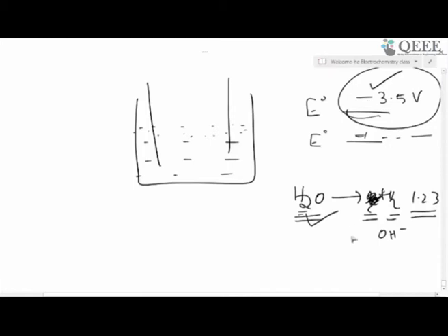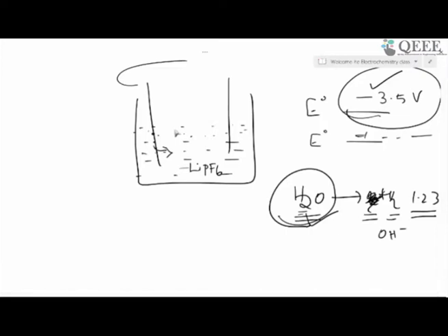To prevent this, we need to use an electrolyte such that this reduction does not happen. So that is why non-aqueous electrolytes with a lithium salt like lithium hexafluorophosphate are used in lithium batteries. But sometimes when you overcharge the battery, the extra charge that you are putting on the electrode may have sufficient energy to react with the electrolyte. So that may lead to some gaseous products, which may build up inside the closed lithium battery, and that may lead to bursting, or some kind of thermal runaway problems.